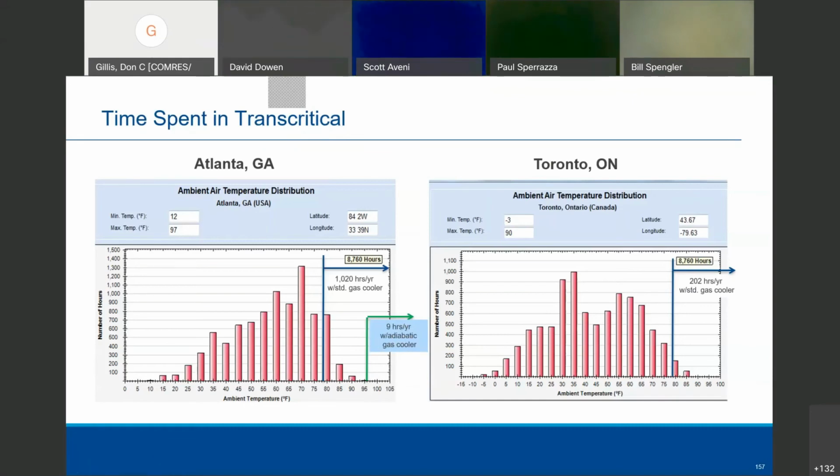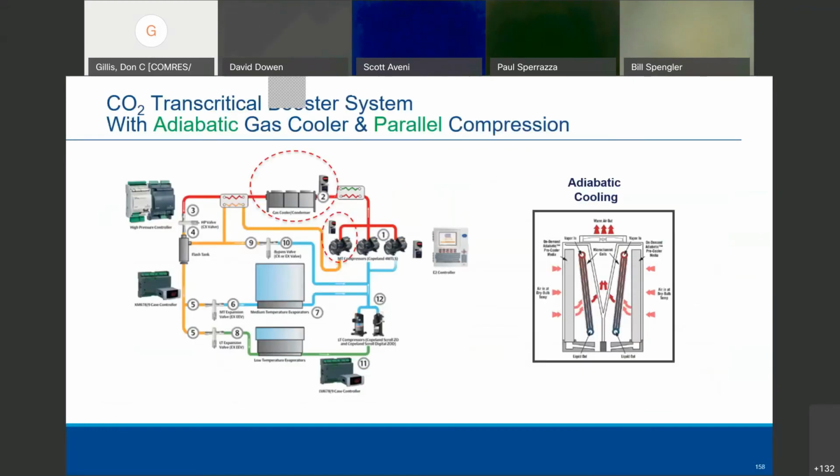So really, the temperature outside, this software is figuring up how many hours we're going to be above transcritical, or above the critical point, okay? So people don't take into consideration how many hours of the year, even if it's typically very hot outside in the summer, we're talking about below that 80 degrees. We're talking about evening, fall, winter. You'd be surprised how many hours you actually can utilize CO2 in the system, okay?